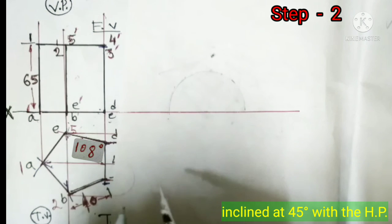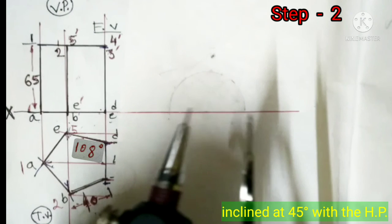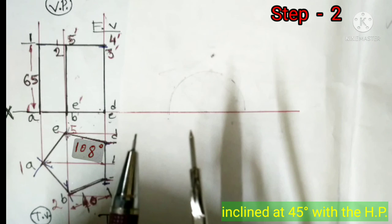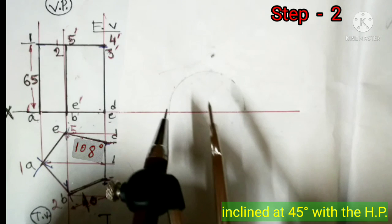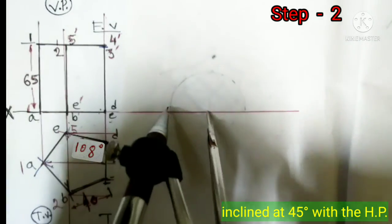Step 2. Inclination with the horizontal plane. As the prism makes an angle of 45 degrees with the horizontal plane, we need to draw an angle of 45 degrees on the VP, because we know that inclination with the HP can be seen in the VP and vice versa.